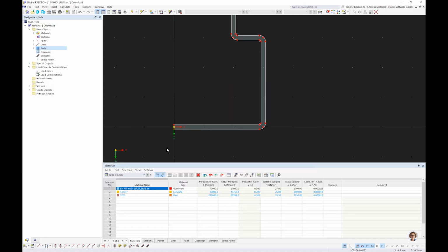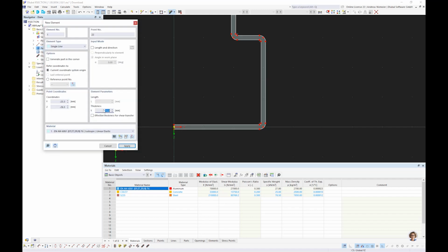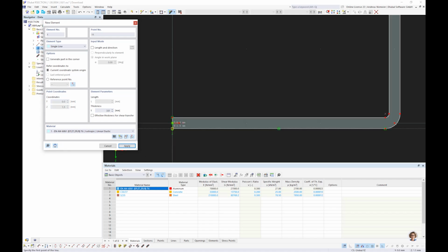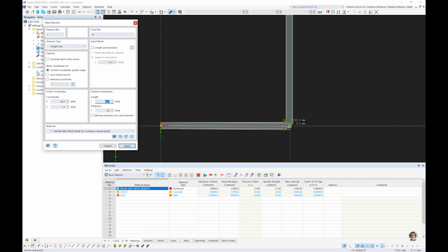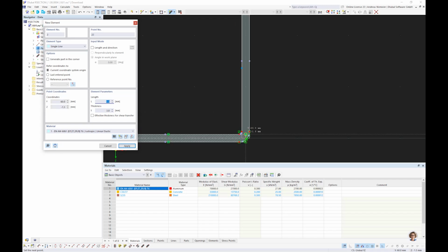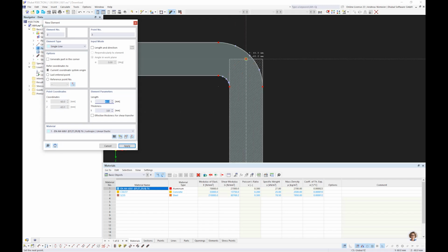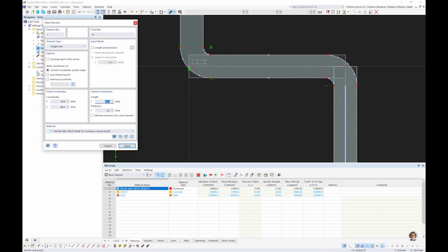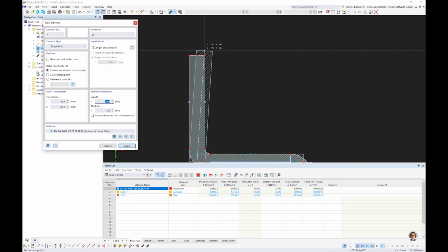And now let's insert these stripes. We can say we have here stripes with a thickness of 3 millimeters from this aluminum, and we insert it, and you see they are really rectangular and have overstand here, but this is no problem because we use a mixed calculation of massive and thin-walled sections.